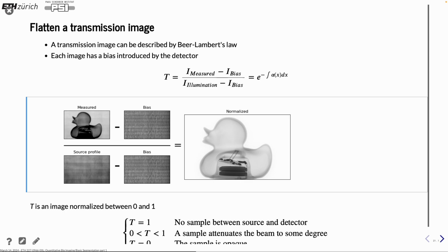It should definitely not vary. The dark current should not vary. So if you set it for one exposure time, you should expect that it gives you, say, 300 gray levels plus minus 10, or something like that. That you must rely on. Otherwise, it's time to change.